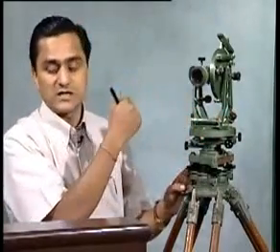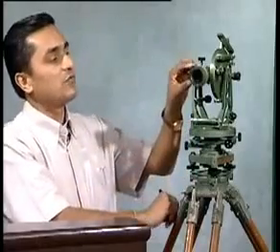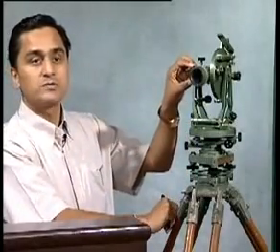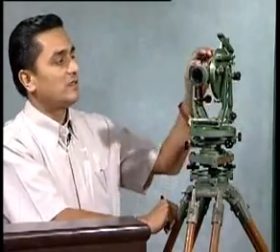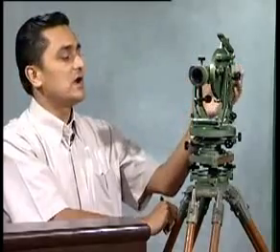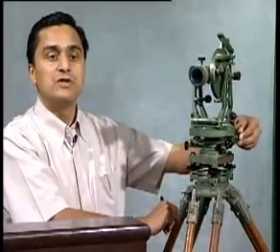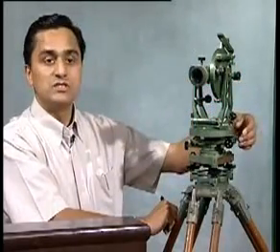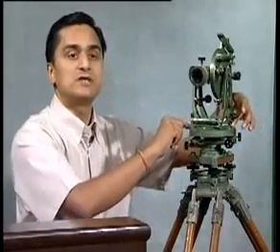But I will need to focus for the object because the object distance may be different, shorter or longer than the object at A. So again I focus for this particular object, and then after focusing it, I bisect it very precisely using the tangent screws, and now I am ready to take the readings in these two verniers again,